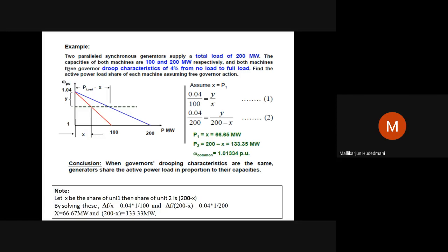In the first problem I took, the frequency dropped to 57.277, something like that. Which was a 60 Hertz requirement, it has dropped to 57. That was going below your base frequency. But this problem has a very narrow load, 200 megawatt. See how the base frequency is very closely managed above the 1 pu value. Let us see how it is being done.